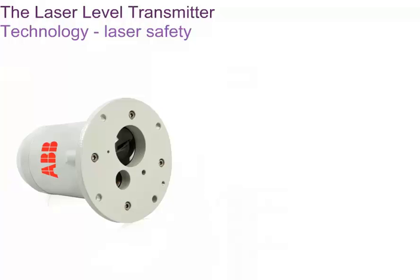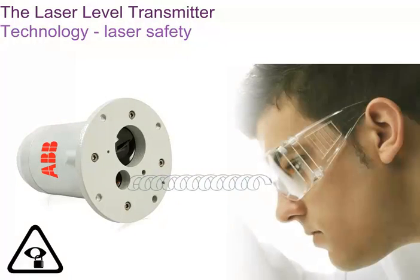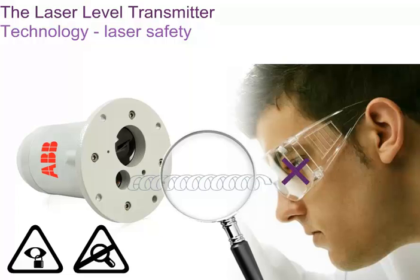Lasers are classified according to their safety, and the laser level transmitter uses the highest safety rating for its invisible measuring beam. This Class 1M laser sends out very low energy pulses that are totally harmless, even if you look directly into the beam. Class 1M devices are considered eye-safe and cannot lead to eye injury unless an optical instrument that focuses down the energy is used.